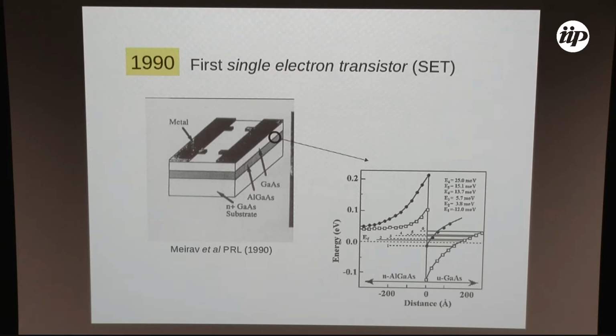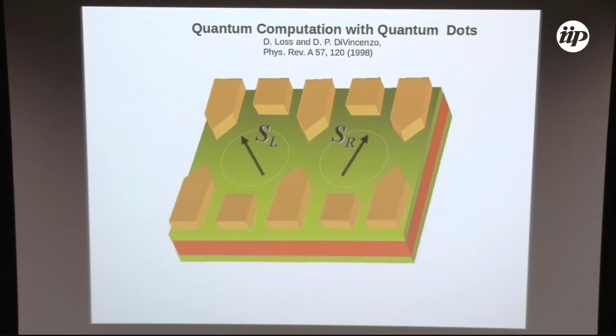And this is a very nice single electron transistor, okay, developed using semiconductor junction. They put metal contacts on top of it, and they can isolate a single electron inside this region here. Okay, so it behaves like an artificial atom that you can control its size, the space between levels, and so on. And this is a good device to build up quantum technology.